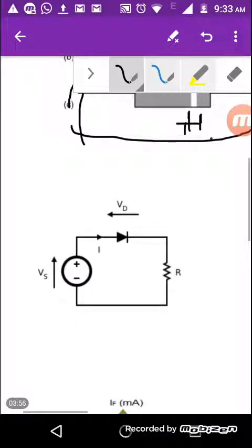And now a simple circuit with a resistor and a diode. When does this diode get into forward bias, and when does it go into reverse bias? We know that there is a barrier between the P and N junction as shown above.